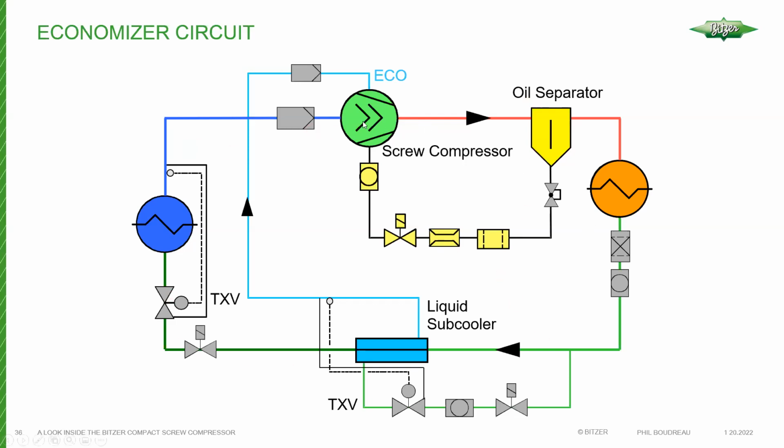since it lays it out quite nicely. So in the compressor, we compress and separate the oil, and then we have refrigerant leaving the discharge port of the compact screw, enters the condenser where it condenses. And then, this could be a water-cooled condenser. If it's an air-cooled condenser, you'll likely have a receiver after that. And then that liquid will travel to the evaporator, okay, where it will be expanded by the thermostatic or electronic expansion valve, which will maintain a superheat at that evaporator outlet. Business as usual here, back into the suction end of the compressor.